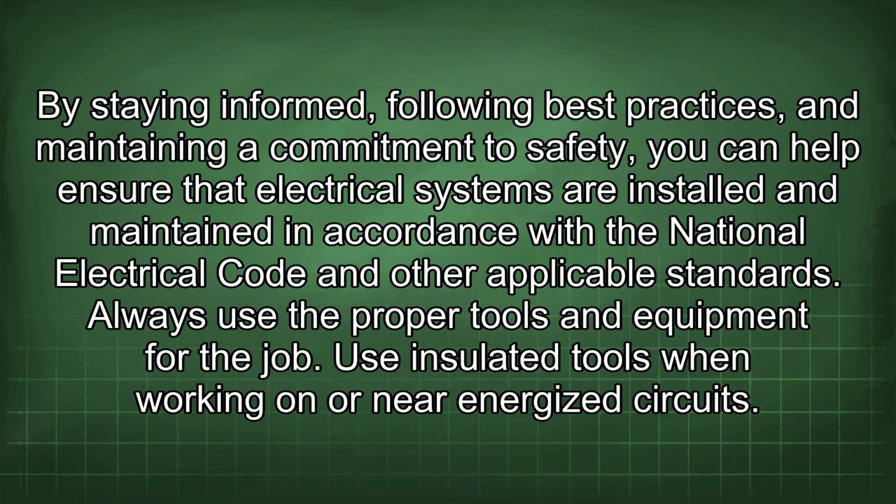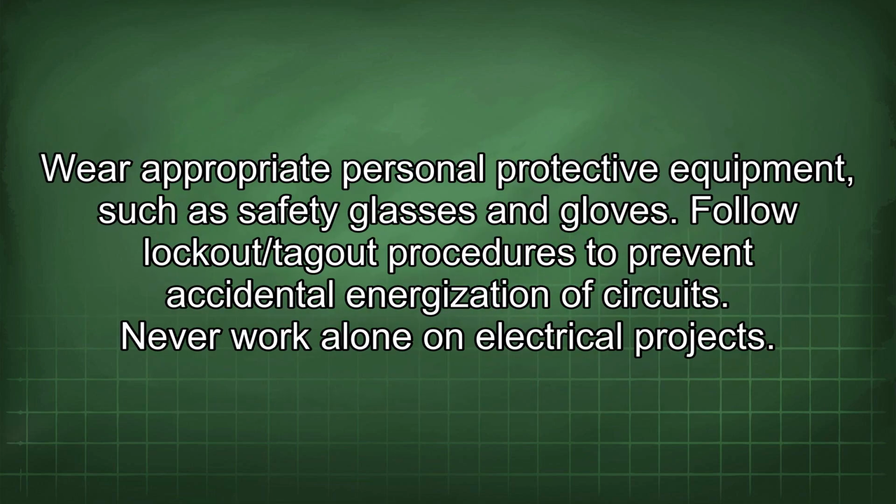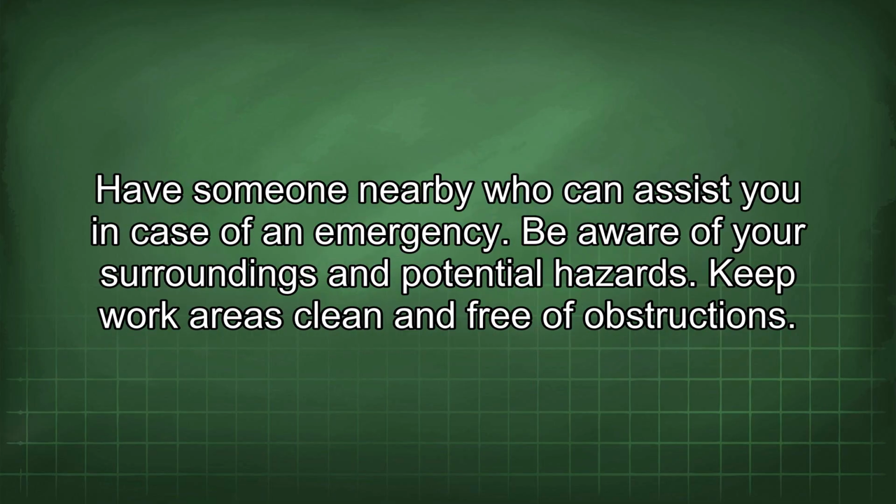Always use the proper tools and equipment for the job. Use insulated tools when working on or near energized circuits. Wear appropriate personal protective equipment, such as safety glasses and gloves. Follow lockout/tagout procedures to prevent accidental energization of circuits. Never work alone on electrical projects. Have someone nearby who can assist you in case of an emergency.